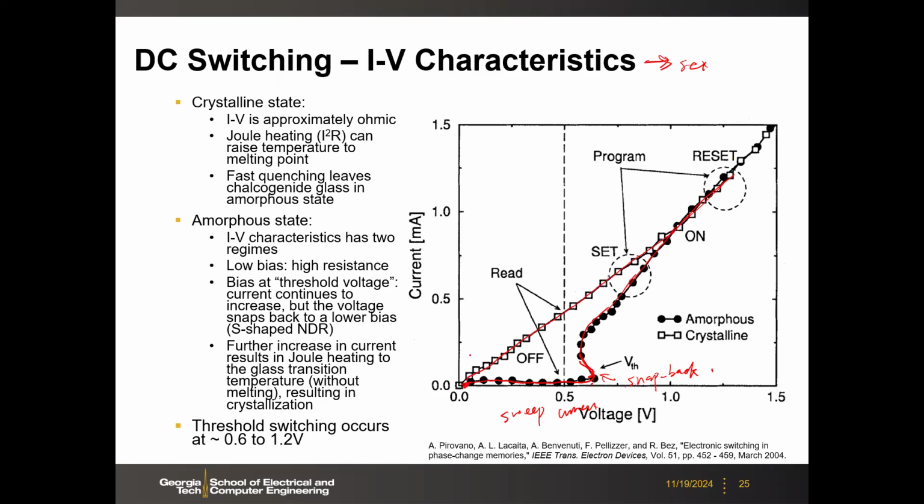Okay. But it's difficult to show the reset here. Actually, you won't see the reset in the DC sweep. Why is that? Any idea? In the DC sweep, you cannot reset the device. Because we said earlier, the reset is a quench process. You have to remove the current very quickly. In the DC sweep, in a typical measurement system, each step takes like a millisecond, and then you sweep this voltage, taking like a few seconds. This won't trigger any reset. Okay.